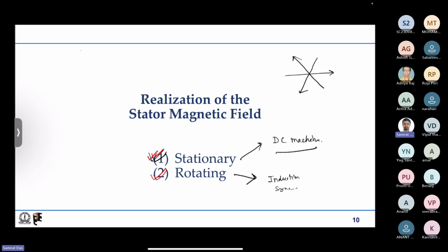So for three phase, we have three axes, 120 degrees phase shifted. For two phase, we will have 90-degree phase shifted axes. If you do the same thing I did earlier, putting some values and pulsations along the axes and taking the net value, the same applies here.